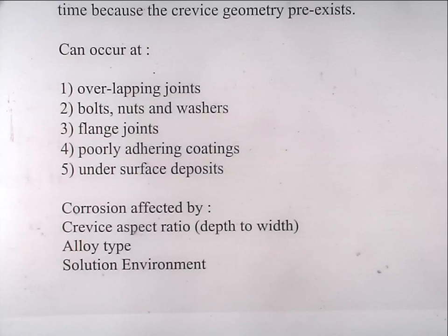So we've got initially anodes and cathodes forming on the surface of one material, and then the anodes and cathodes moving to areas of low oxygen in the case of the anode situation, and high oxygen in the case of the cathode process.